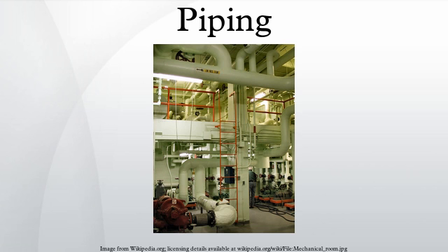Materials. The material with which a pipe is manufactured often forms the basis for choosing any pipe. Materials that are used for manufacturing pipes include carbon steel, ASTM A252 spec grade 1, grade 2, grade 3 steel pile pipe, low-temperature service carbon steel, stainless steel, non-ferrous metals, for example cupronickel, non-metallic, for example tempered glass. Standards. There are certain standard codes that need to be followed while designing or manufacturing any piping system.